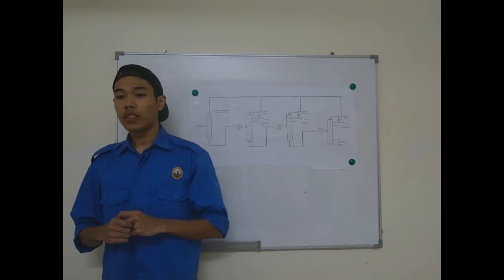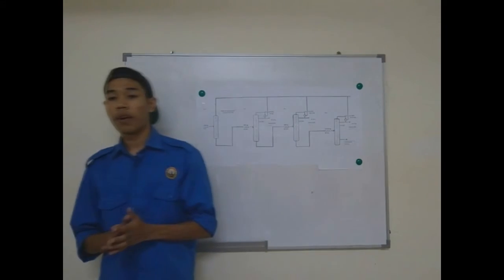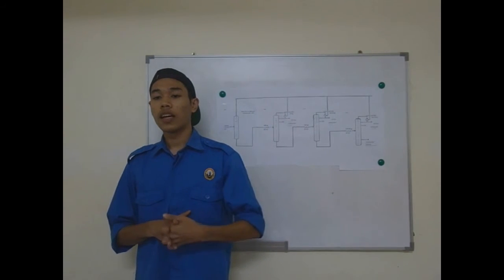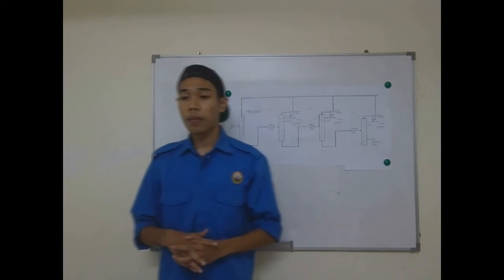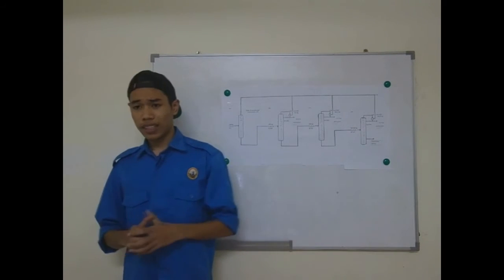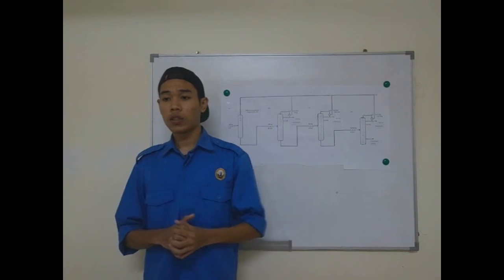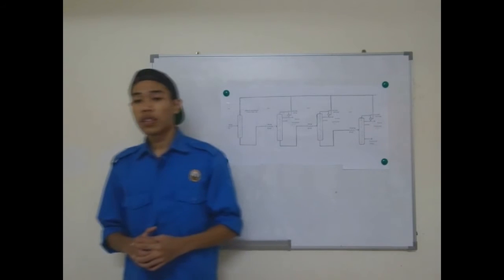Sulfonic-based polystyrene resin catalyst is used in esterification of fatty acid, and copper chromite, copper zinc catalyst in high pressure hydrogenation of methyl ester of fatty acid to produce fatty alcohol. To maintain catalyst life, it is crucial to ensure the absence of catalyst poisons and inhibitors in the feed.